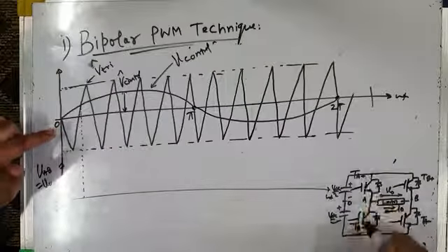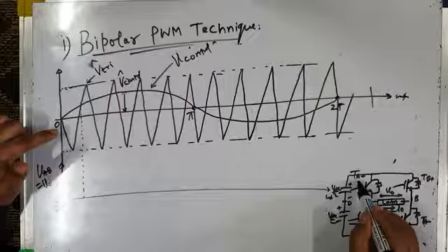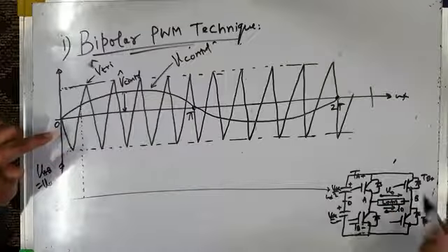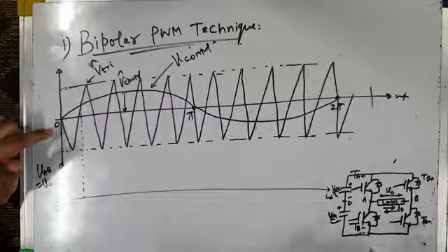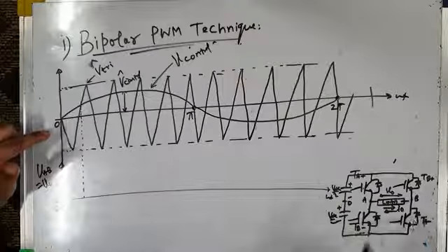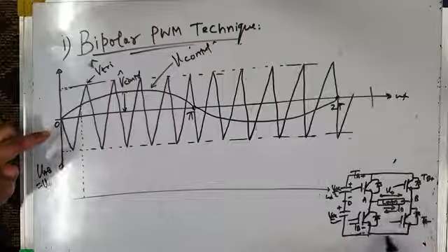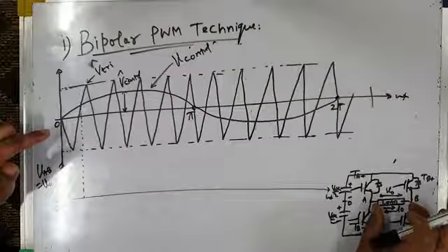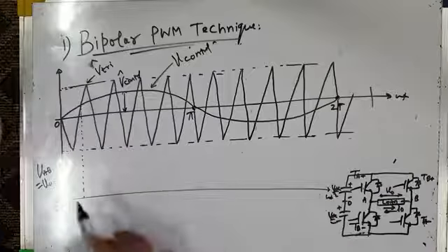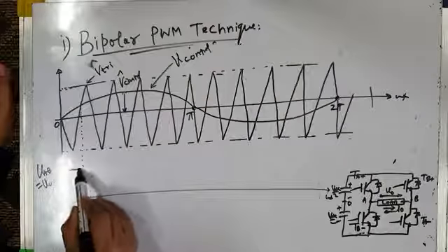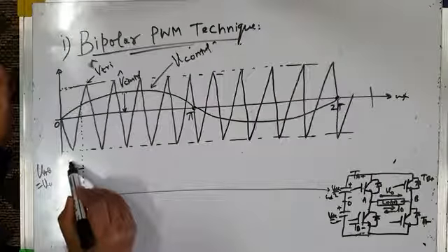So therefore in this leg the upper switch TA plus is on, and in this leg the lower switch TB minus is on. So this is on, this is on. So A gets connected to the positive DC bus, B gets connected to the negative DC bus. What is the total load voltage VAB? It is plus VDC. So this is my load voltage. It is plus VDC.